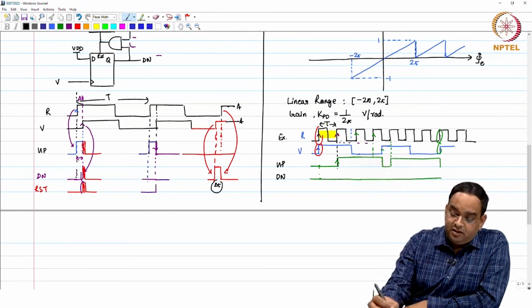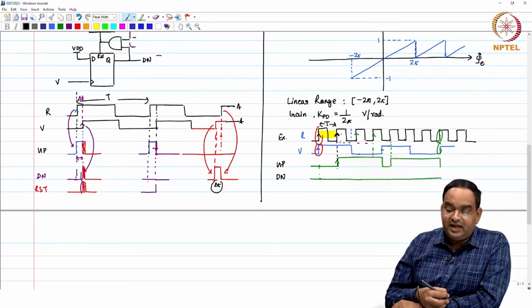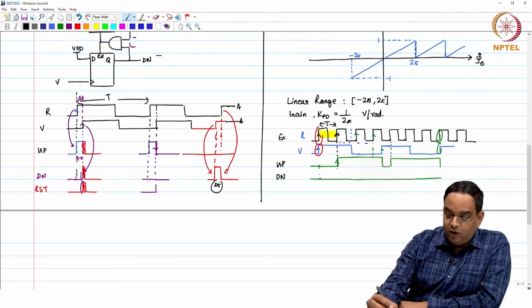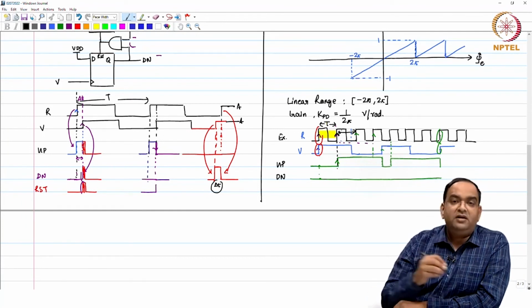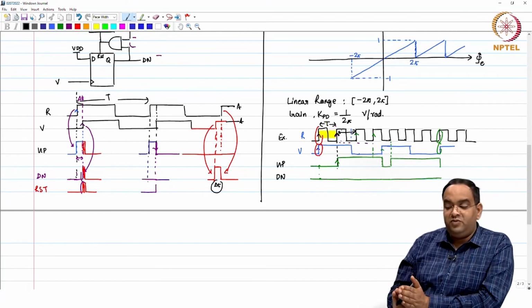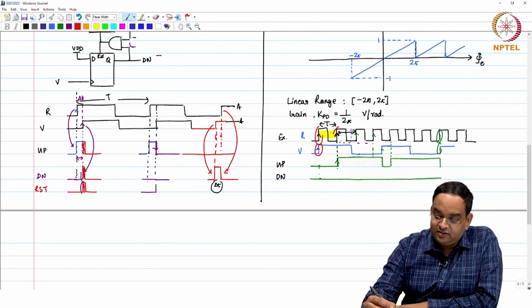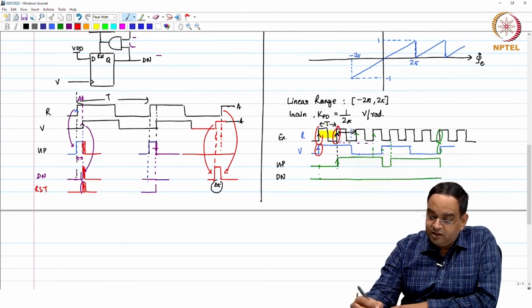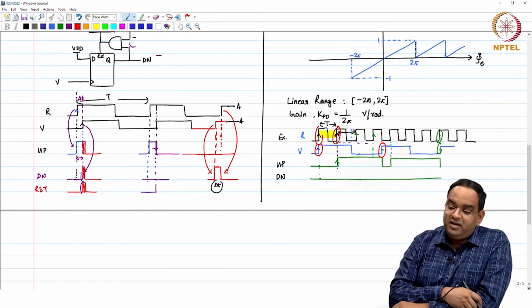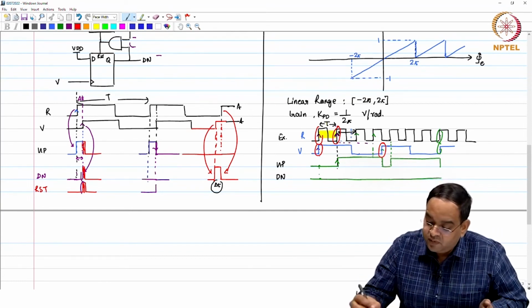And then if you look at the second rising edge on R, in this whole period, you do not find a rising edge of V. So, your error between the two rising edges, when you get this one and when you get here, is like 2.5 clock period at TV. This is my phase error.